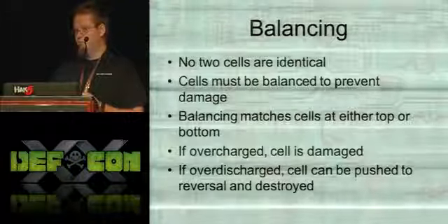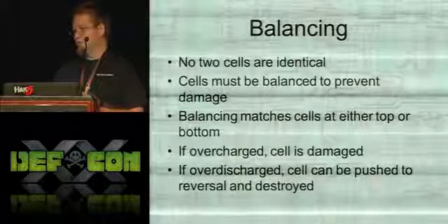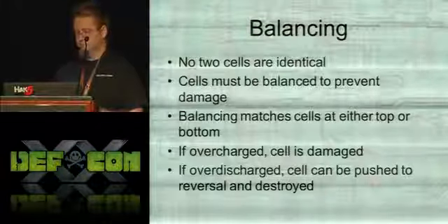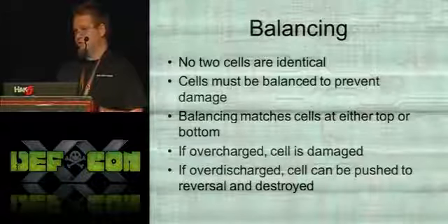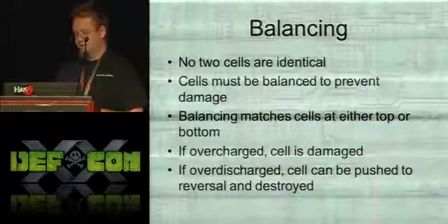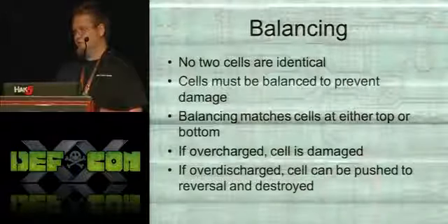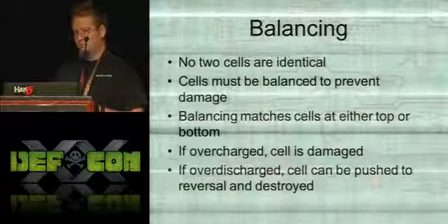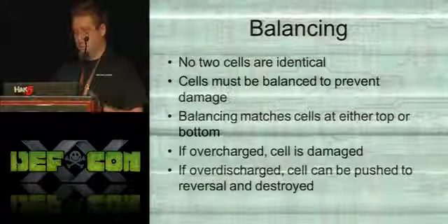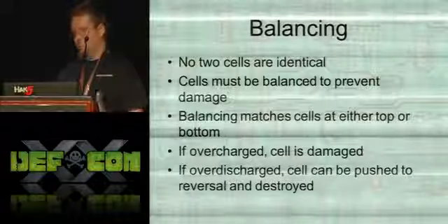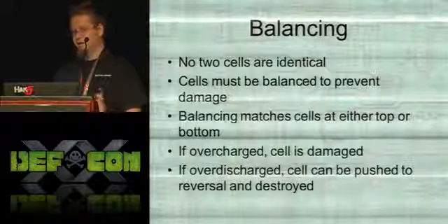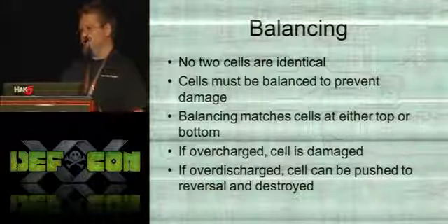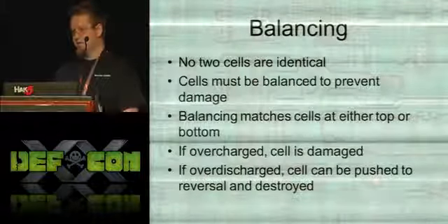Right now, people are expecting to only have to do it once for the lifetime of your batteries. We'll wait and see if they ever drift, but for now, most people are experiencing that they can run them for years, and they don't drift at all after they've been properly balanced. Because the charge curve is so flat, you have to do it at either the top or the bottom. And by matching them all the same, you can make it so you can really charge your pack to near capacity without damaging anything. One really easy way to stay safe is to just stay away from the ends.